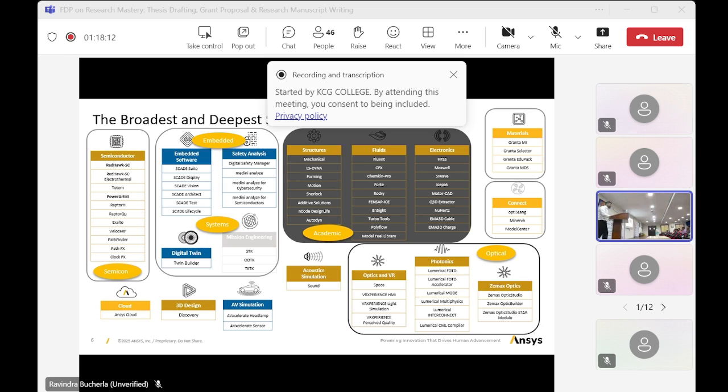It should be lightweight and have enough strength so that it will not break when flying, and it should not be so flexible that the wings deflect more when wind load is acting on it. Based upon these parameters, how are you going to select a suitable material?